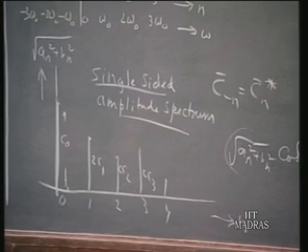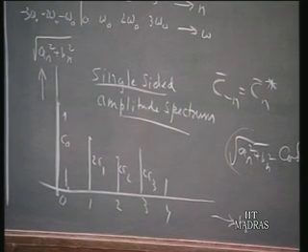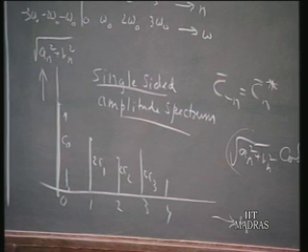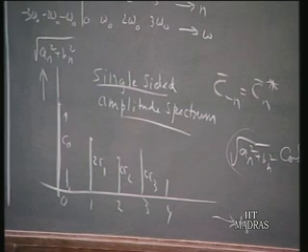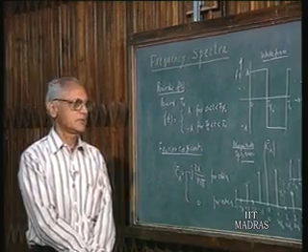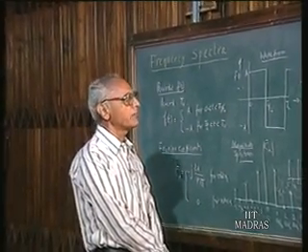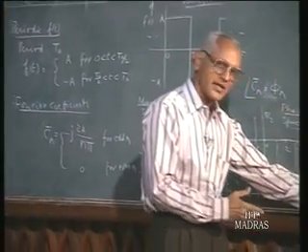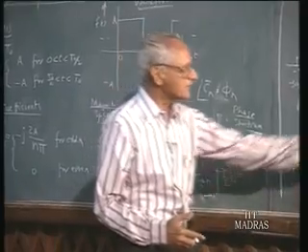Okay, so the concept of spectra is just a way of indicating the various harmonic coefficients in a pictorial way. Since each harmonic coefficient is associated with two quantities, either an or bn, or the magnitude of Cn and the phase of Cn. For example, if you choose to plot in this fashion, the angle information is once again this.